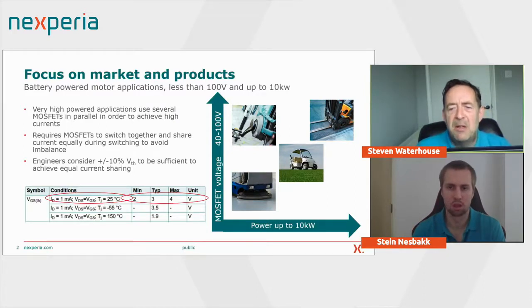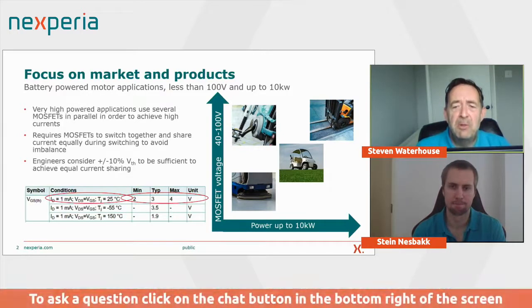If you imagine a forklift truck with a 10 kilowatt drive on it, it's got to move some very heavy material, and this may require maybe 100, 200 MOSFETs to drive that motor, and a lot of those MOSFETs are connected in parallel.